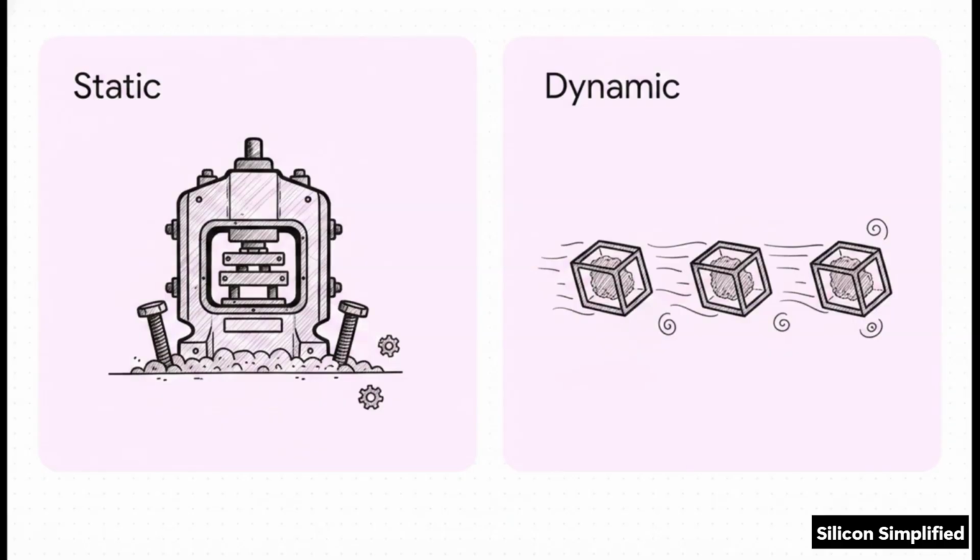The entire UVM testbench architecture relies on this strict dichotomy between two main base classes. On one side, you have the UVM underscore component. These are your static structural elements, stuff like your environment, agents, and scoreboards. They get built at time zero, and they stick around for the entire simulation.